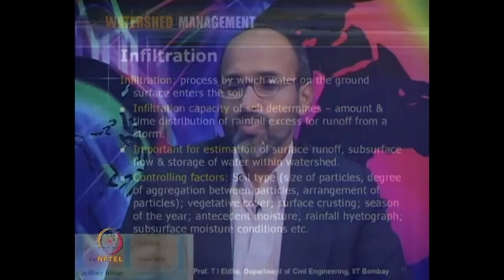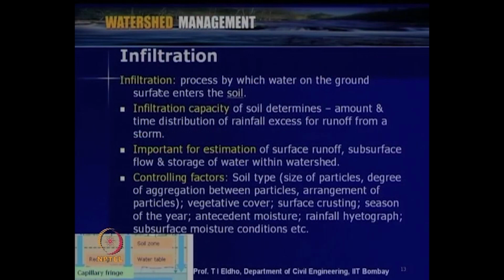And then the next, very important hydrologic process is so-called infiltration. That is one of the most important hydrologic processes, which decides how much will be the water loss when we consider precipitation to runoff. Actually, it is not a loss, it is going to the earth, through the soil to the aquifer system. So, this infiltration we will now discuss in detail.